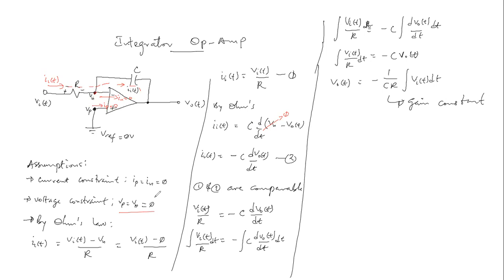And in the S domain, we can actually place the transfer function, or the system function. So, the transfer function in the S domain, which is equivalent to the Laplace transform of V naught over V in, that is, the ratio of the output to the input, will give us negative 1 over RC, right? Which is the same, then S.